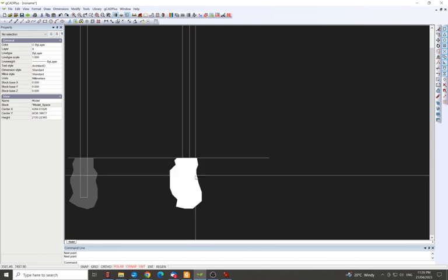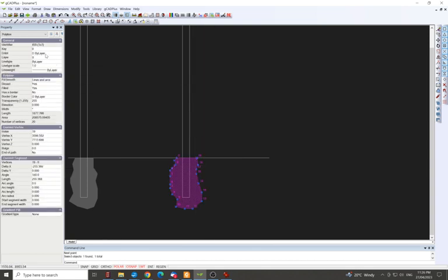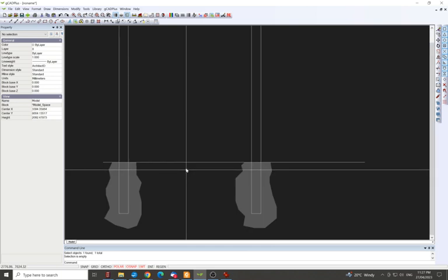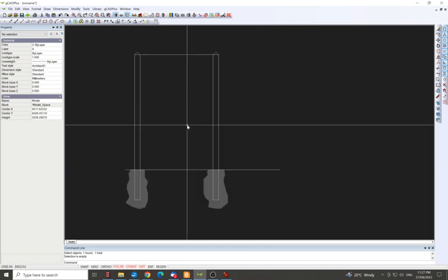Enter filled. Grab that. We'll change the color here if you wanted to. 253 is the last color we used. Transparencies are here. Knock that up from 255. I don't know what 255 means. I think they're just the max values. From 1 to 255 is a transparency, 1 being basically no color, to 255 being almost solid, and 100 always seems to be a good number to use. So there's our concrete footings.